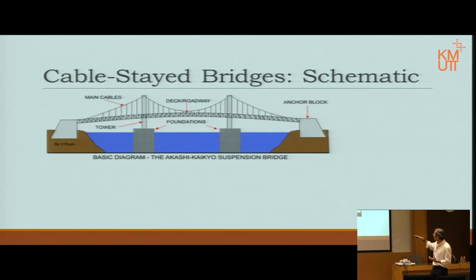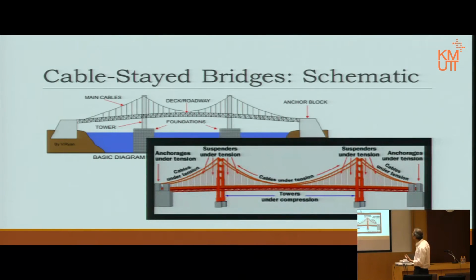Now the cable system on the top will be the main cable, the one that goes on the top, connecting like the framework of the load transfer. If we look in more detail, the one that is vertical, the vertical cable, is sometimes called suspenders, sometimes called secondary cable or vertical cables. The idea is that rather than all the weight going down to the two anchors and the two foundations alone, it actually goes straight upwards to the cable first, and you see the system of load transfer. Then the main cable takes this load and pulls it into the anchorage there.